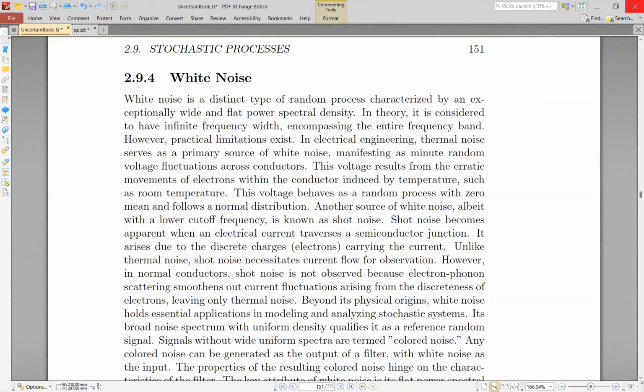I started because I would like to emphasize the important things in random processes, like stationarity, ergodicity, non-stationary processes, and then the autocorrelation function, and the Fourier transform of autocorrelation gives us the power spectral density. The power spectral density is the distribution of the power over frequency of random signals. So all these are very important. After the break, we come to study what white noise is, and after that we start to present some of the important dynamics in random processes.